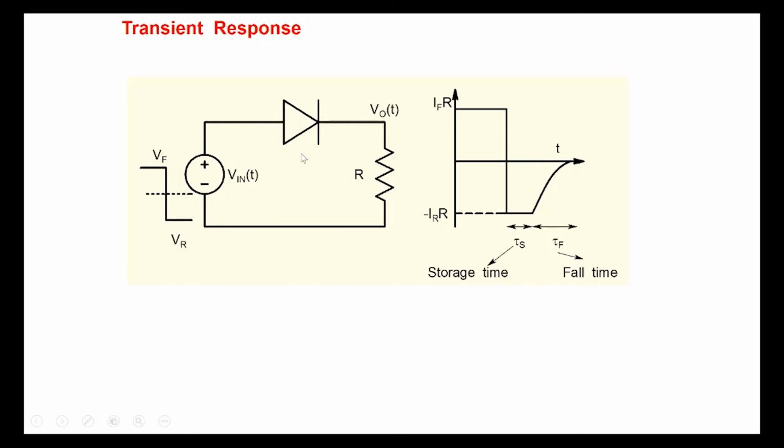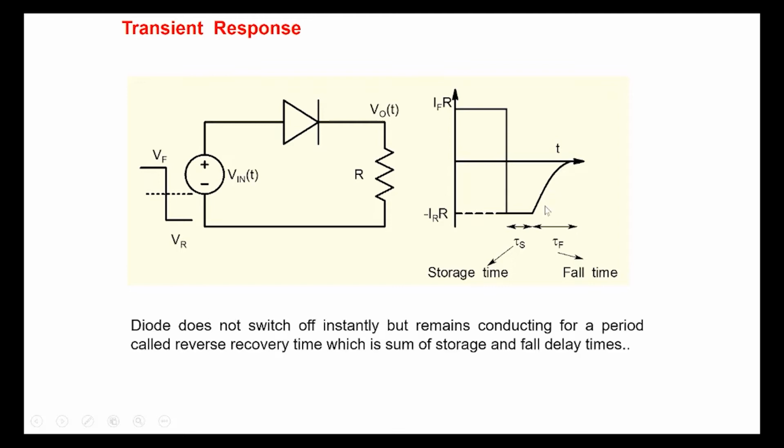And before we leave this particular topic, diodes are often characterized by what we call the reverse recovery time. When you switch the voltage across a diode, going from forward bias to reverse bias in a circuit like this, the diode conducts in the reverse bias direction for a period of time, which we call the reverse recovery time. It is the time it takes for the diode to recover back to its blocking state, a low current state. So it takes a certain time to get there, and diodes are characterized by a reverse recovery time, and the manufacturers of the diode will provide you with data regarding that.